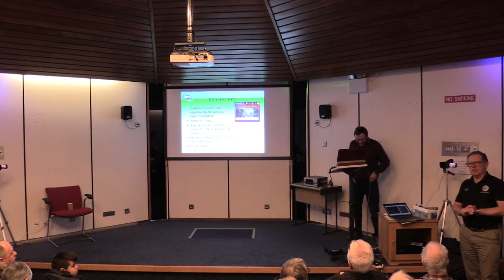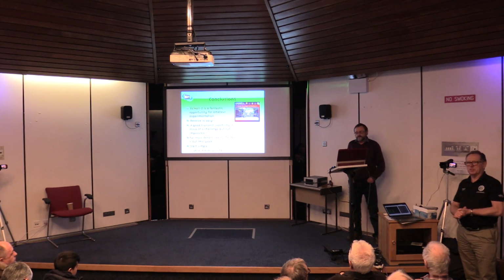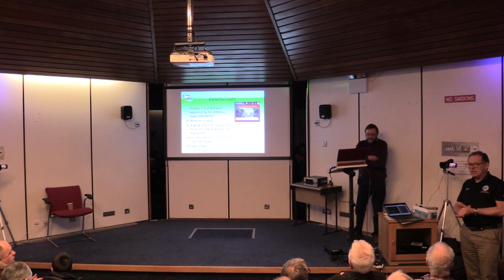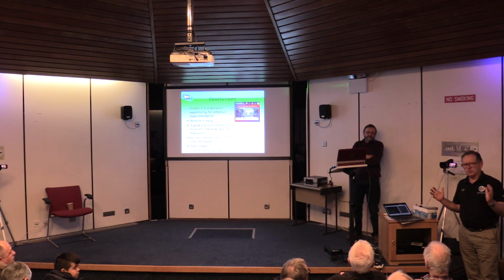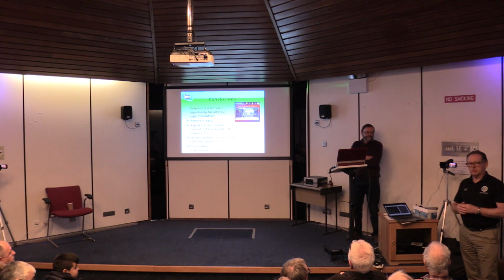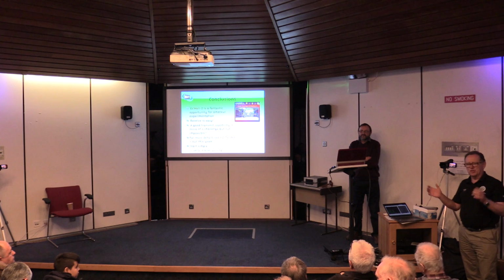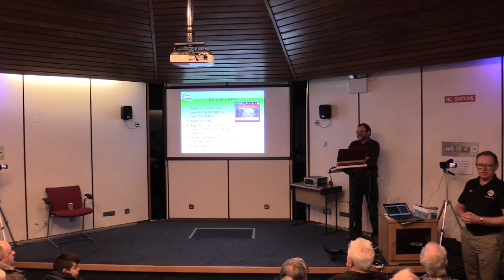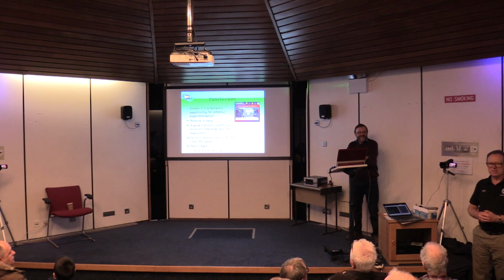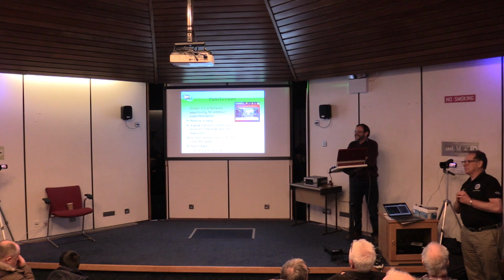You can actually go below the 2.4 gig frequency, which is the cutoff of the amateur satellite service spectrum, so that would really, really be naughty. Please control your transmissions to, as it says, within the beacons, and then they know what's going on. There are technical reasons why that is the preferred method of operation. Nobody will answer you if you're outside it.